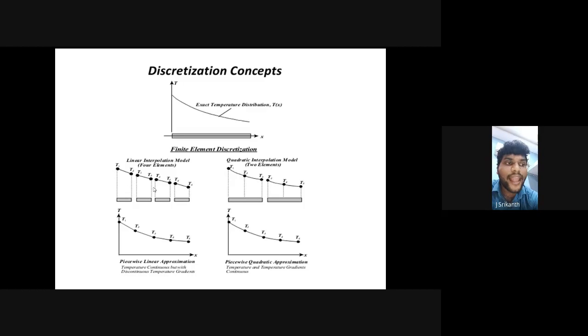These whole elements will be included in this particular body. For example, this is the body. The curve is the body. The body is also called a structure. In this particular structure, to find the stress analysis, displacement analysis, and strain analysis is very difficult. At that time, we choose finite element method discretization. With the help of finite element method discretization, this whole body is divided into smaller elements, number 1, 2, 3, 4. So the whole body will be divided into 4 elements.